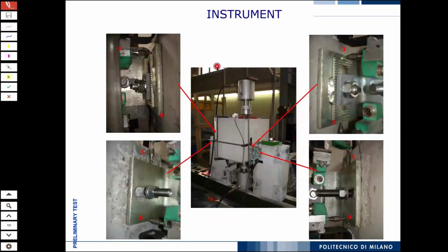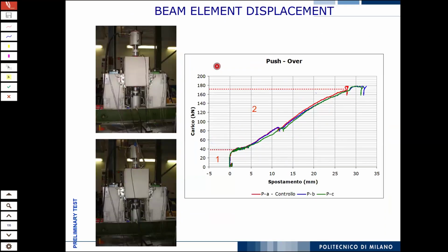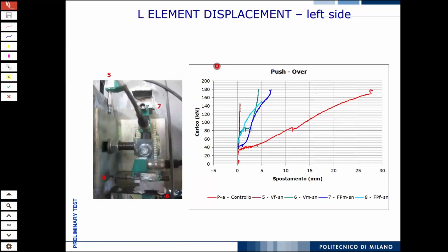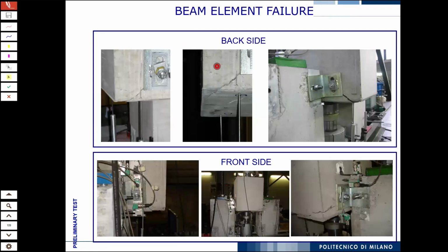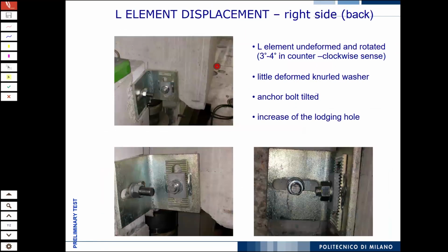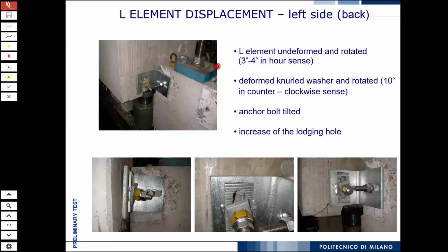These are some images that we had. This was the case in which we had a very, very thick steel angle profile. And we had this response, cracking, some kind of nonlinear response, but we did not exploit the full yielding of the connection. We had the splitting failure of the concrete block. And we said, well, why don't we go thinner?